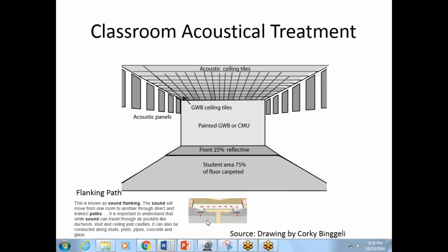So this just shows you that we have to think about all those contact points. We have to think about the air ducts as a possible way that sound's going to get transmitted between spaces. We have to think about just the flex in the wood and the wall planums and them being in close proximity to each other in these corners.